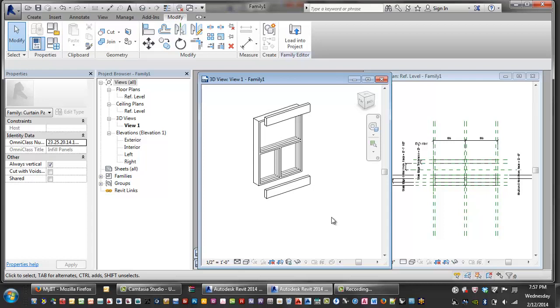And then these two, right? These are operating in that same fashion, where I need to think about if I'm stacking this up, all of a sudden I'm going to have duplicate data over the top of each other. So I need to separate out my slab edge covers into individual pieces and then assign visibility parameters to those. And then in a certain family type, one will be on, and in another family type, another one will be off.